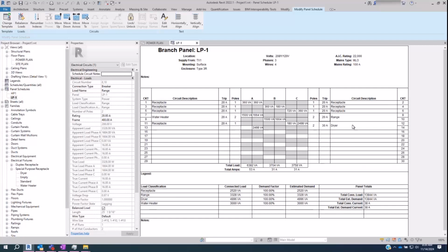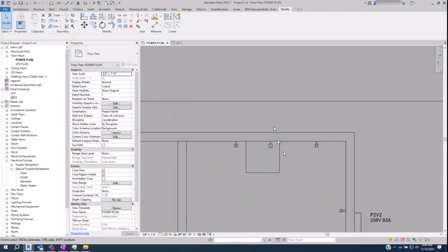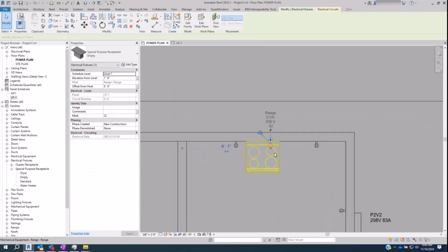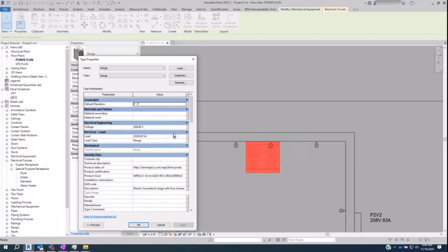Yes, we can stay at a 20 amp breaker. And for the record, that is a really small oven. Normally I would expect that to be a 40 amp breaker. But yeah, in this example, it's a baby oven and doesn't have that much load. Right. Yeah. Just to make it a little bit more realistic, let's bump it up.